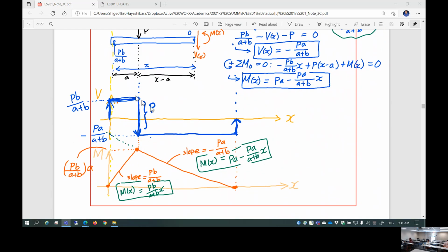And after you complete shear diagram, based on that, you're going to construct the moment diagram. Starting from 0, shear is a constant value. That means the slope is constant, positive from here all the way to here. Now, all of a sudden here, shear becomes negative. That means the negative slope constant all the way back to 0. Okay? So obviously, you can construct this shear and moment diagram by using only that handout. So important thing is, please bring your handout with you and then take a look at it all the time, because that's the only information you can access.